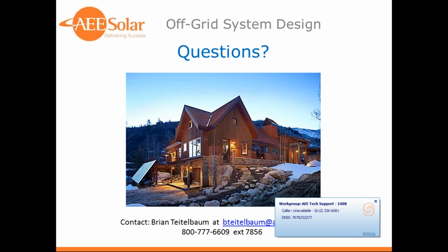They can automatically start the generator based on battery voltage. There are a few systems that also use amperage or battery capacity calculations in their equipment that can be programmed to do that. So yeah, it can certainly be automated to the point where if your PV or other renewable energy sources aren't keeping your battery topped up enough, battery voltage drops to a certain point and the battery capacity drops to a certain point, that the generator can be automatically started.